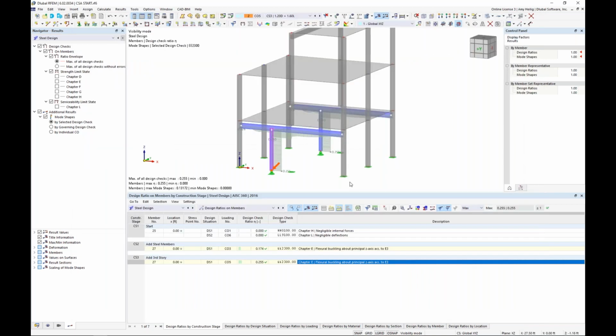Okay, so this will sum up the example today where we have modeled the entire structure. We created those construction stages not only for the model where we deactivated elements and activated other elements, but also the loading considerations, where we need to factor in the construction stages to the load combinations and our design situations. And finally, we saw how we can incorporate those stages into the additional